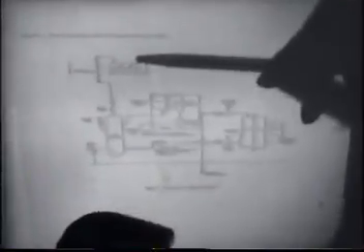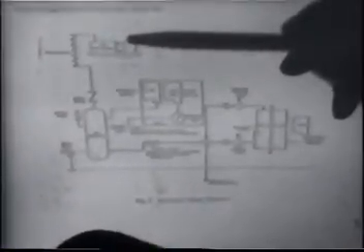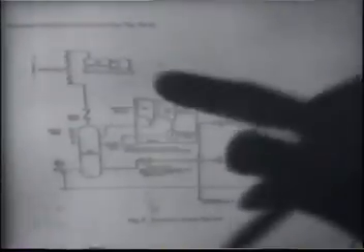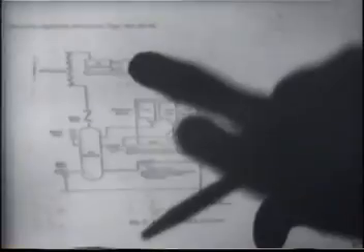This is a schematic of what a pneumatic operating mechanism looks like. We have an air compressor in each control compartment that's powered by an AC motor, and in turn it compresses the air up to pressure. On most of our circuit breakers, it's in the order of 250 psi. On our 345 kV breakers, we have several systems, but we compress at about 2,500 psi, and then we reduce it.